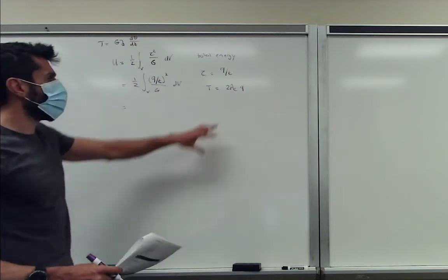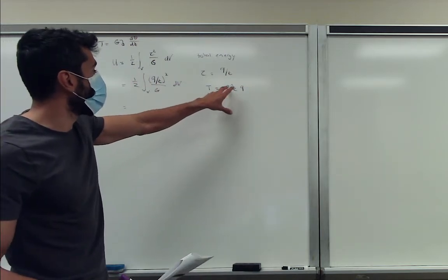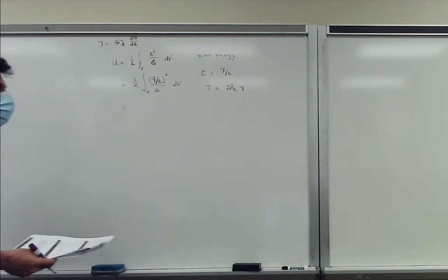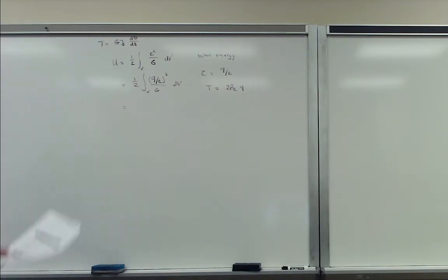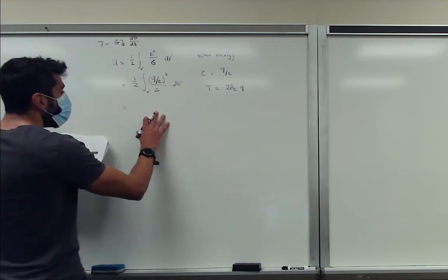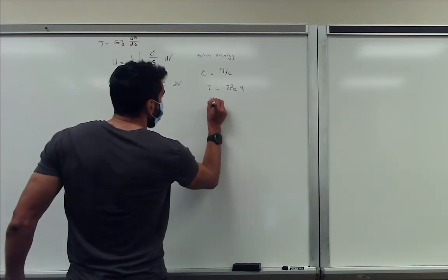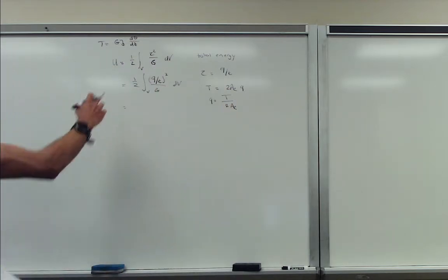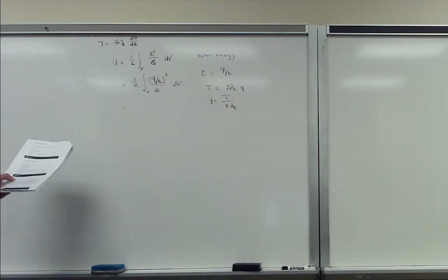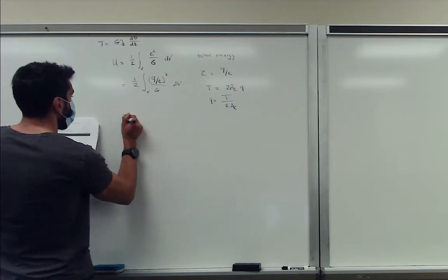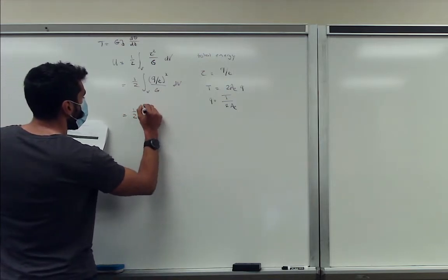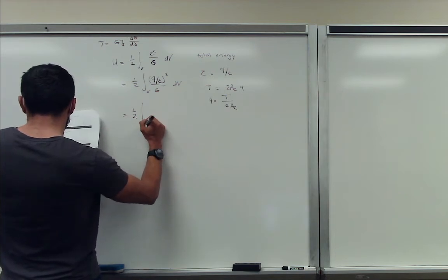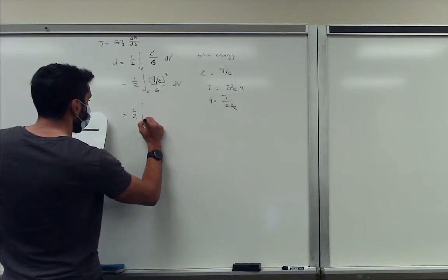And by the way, sometimes I forget the subscript E, but in this case it basically refers to the enclosed area. So let's do that. What we get is, we can rewrite this as q is equal to T over 2AE. We can substitute that back in. And what we get is, let's do the volume still.